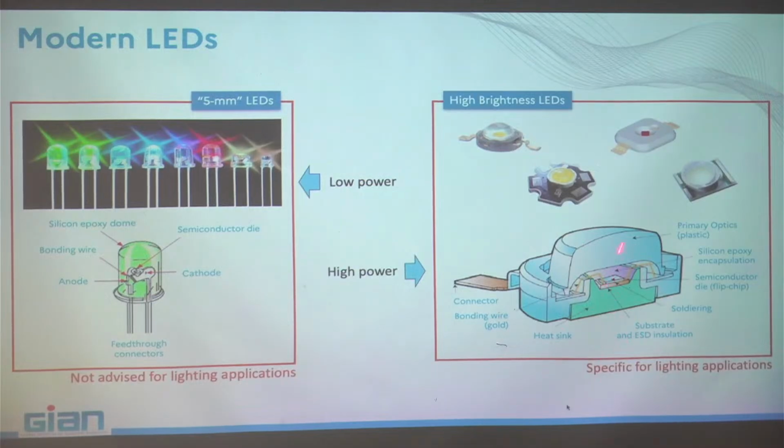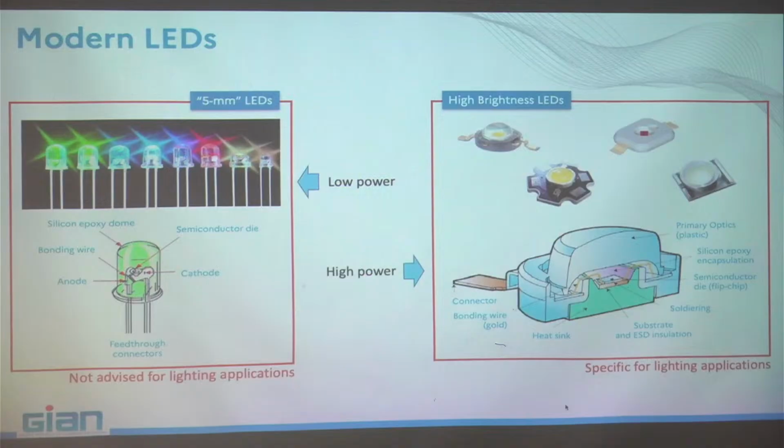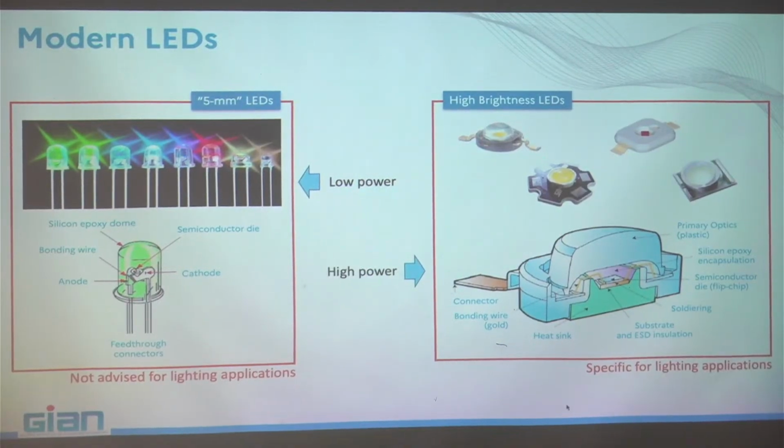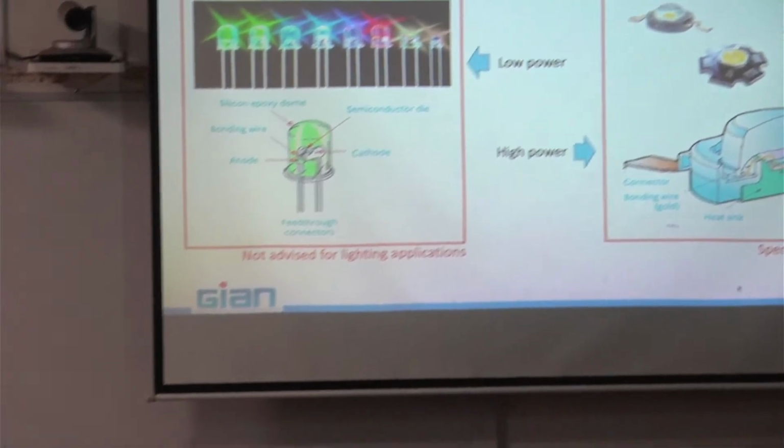power. The size of the crystal for an LED of 1 watt is around 1 millimeter square, 1 millimeter by 1 millimeter. These kinds of chips can go up, in a single chip, to 5 watts. There were some 5 watt single chip LEDs produced at the beginning of the 2000s by Philips, and many of them were used to illuminate the Shanghai TV tower.